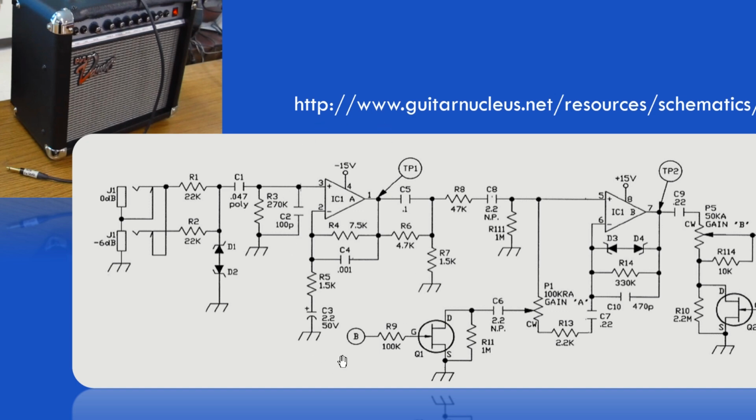And then we talked about how this circuit here around IC1 is forming a voltage amplifier with a gain of, I think it was about 6. And so the output is here. And that's a low impedance output. That's going to be very important, as we're going to see. What happens next is it goes through this interesting circuit, and that's the one we're going to study today.